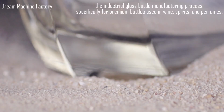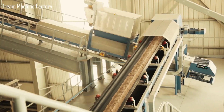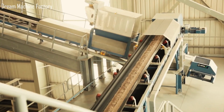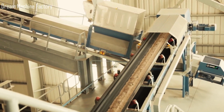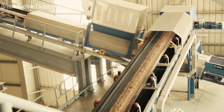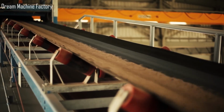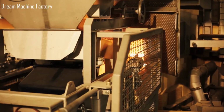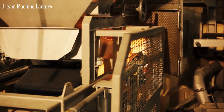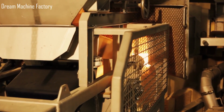It begins with the careful selection of raw materials. The primary components are extremely pure sand, soda, and lime, which make up about 95% of the mix. The remaining 5% consists of additives that influence the glass's mechanical, chemical, and optical properties, as well as its melting and refining characteristics. Recycled glass, known as cullet, is added to reduce energy consumption and raw material use. These materials are transported on conveyor belts to mixers, producing a homogeneous batch ready for melting.